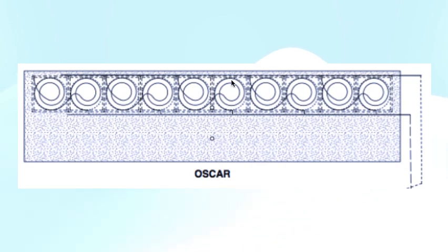But you'll also notice that when talking about contour, if the slope is here, we only want the slope coming from up here down here. We don't want it from up here down diagonal-wise. That's when you end up having water collecting in one corner, potentially ponding and that sort of thing. So we want the coils all in one line, but if it's to be on contour, this needs to be slightly curved. That's fine. That's completely doable, but on contour, that's non-negotiable.